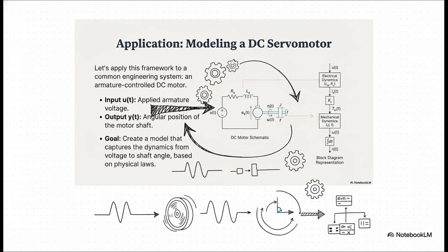Okay, to make this real, let's think about a simple DC motor. The input, U, would just be the voltage we apply, and the state, X, could be the shaft's angle and how fast it's spinning. By using the laws of mechanics and electromagnetism, we can figure out the F and G matrices that perfectly define this relationship. This is the ideal scenario, a model built on pure physics. But reality is always a little more complicated, isn't it?